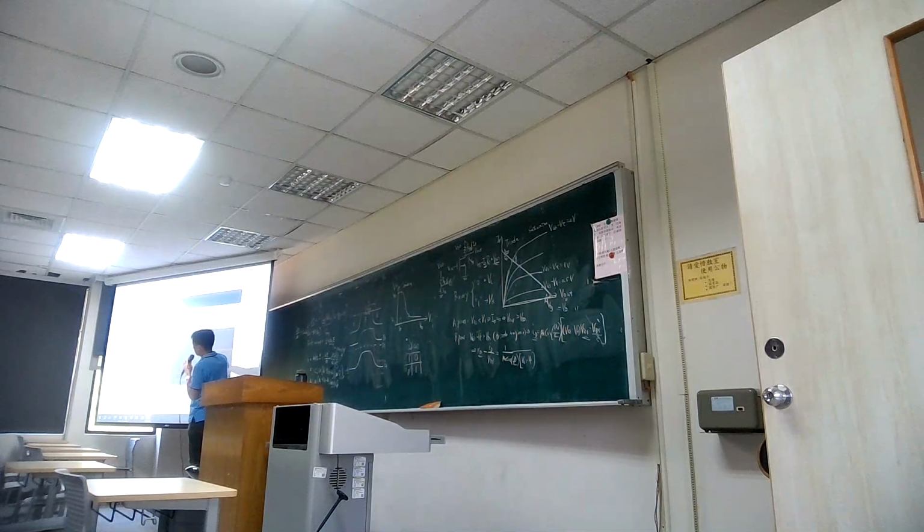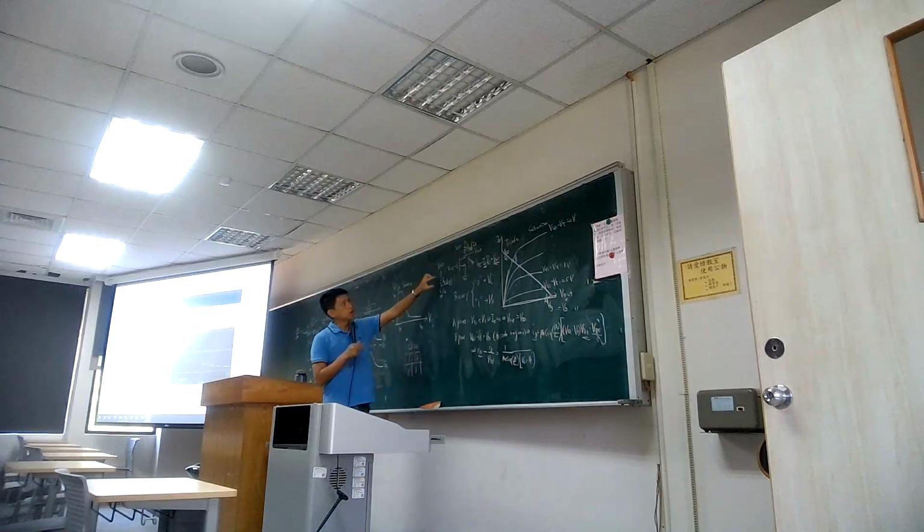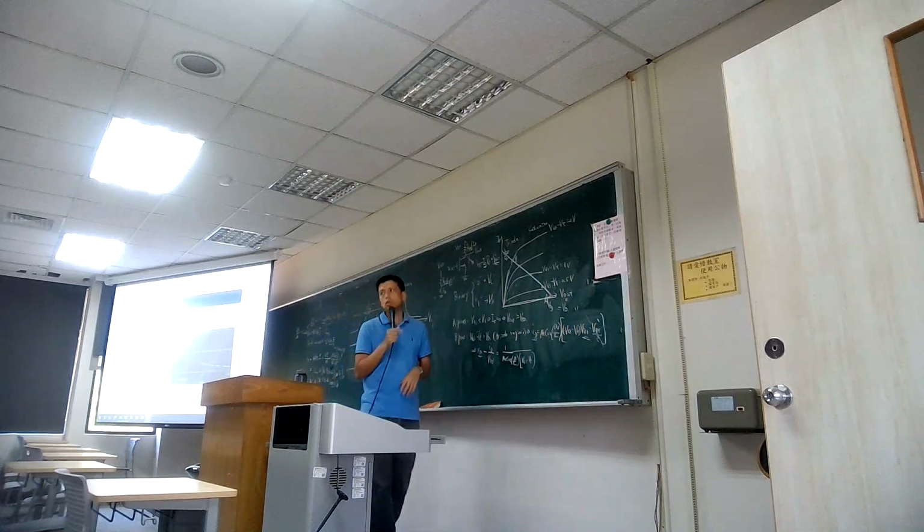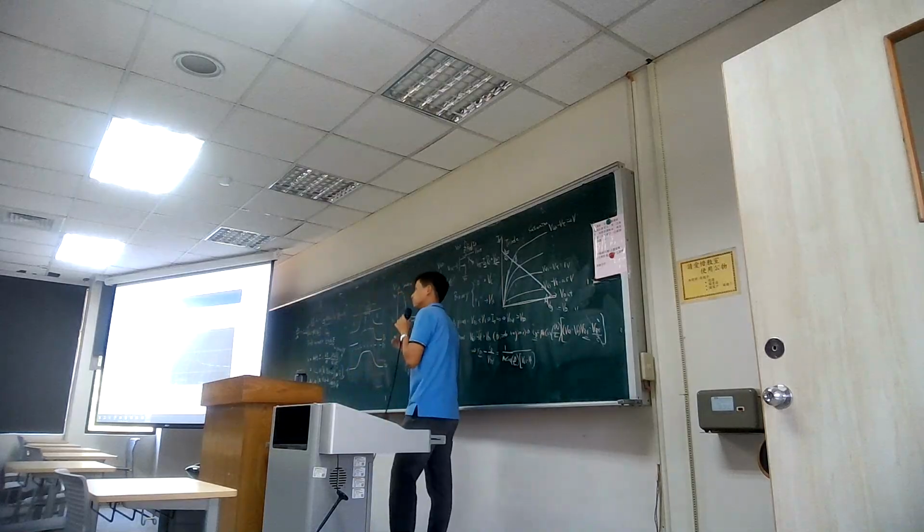But you can also see that if you work in the triode region, the voltage is low, less than 1 volt, depending on the resistance you apply there. You can replace it with a different resistance; with a higher resistance, you get a higher load line. When you are working in the triode region, it's just like a voltage divider. If you increase the RD, most of the voltage drop will be across RD instead of RDS, so you can minimize your output.